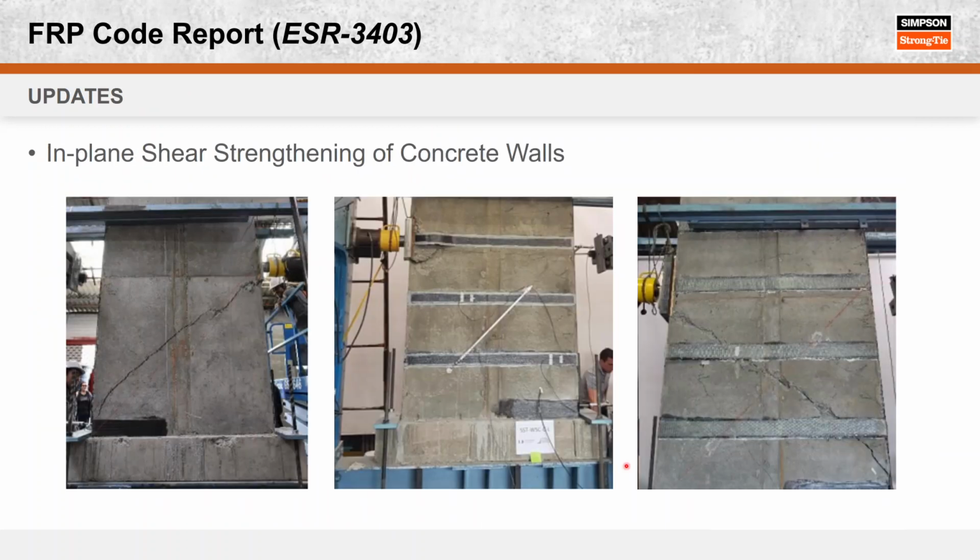We'll go back. But so these are the wall specimens with no anchors, but we're going to do wall specimens with FRP anchors and see if we get better results and see if we get high strains, so we can adjust our design procedures. So Aniket's going to go, this is in the country of Colombia in South America, and Aniket's going to go watch the testing because he's got all this free time.